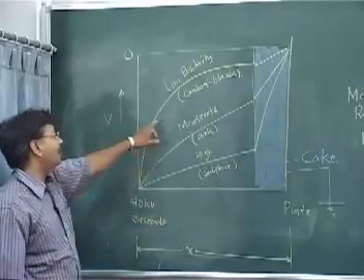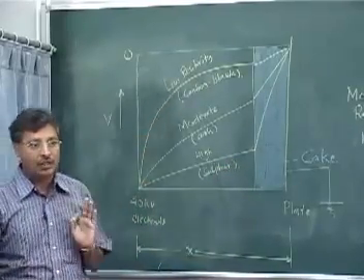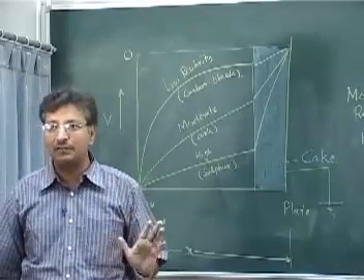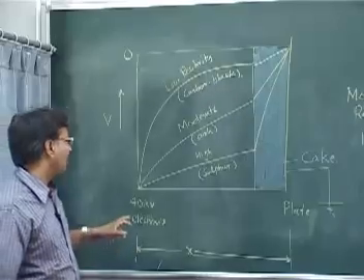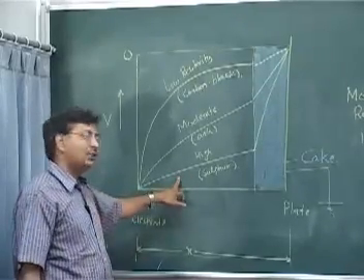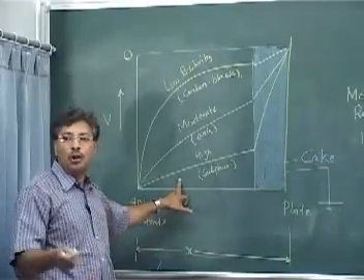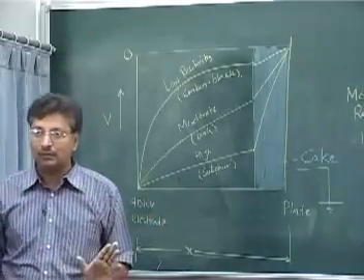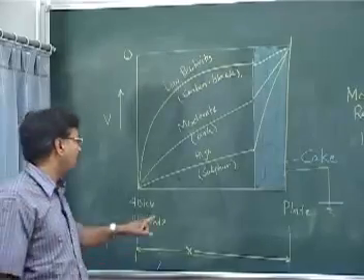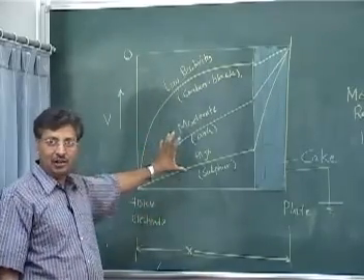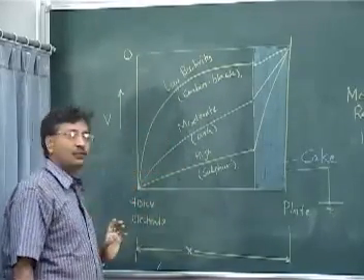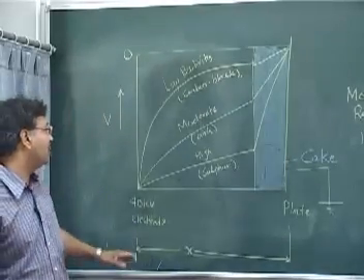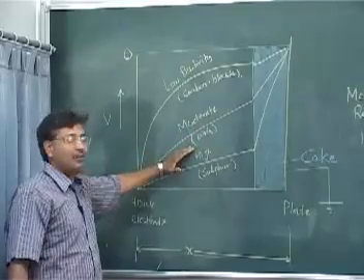So if you are dealing with the carbon black, you go to the carbon black industry, they will not talk to you about ESP. They will talk about bag filters that we have not talked about. You go to other things where the sulfur is there, suppose in your ore or in your process sulfur is there, they say, oh well, we are not going to use this one. Okay. So they don't use this one. So for the ash or ash kind of substances, it works very well. But unfortunately, Indian ash has a low resistivity. So that will fall somewhere in between.